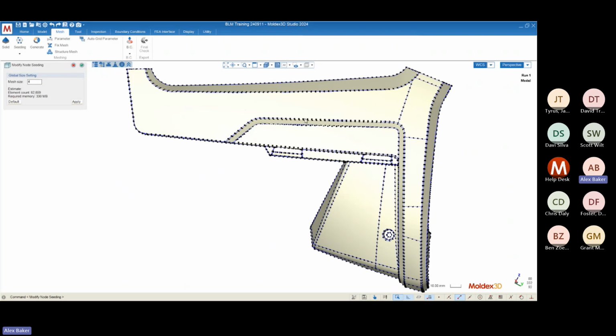But if you use this approach, you'll get more or less a perfect trade-off between the geometry approximation and simulation. I would say that the mesh size of 4 is pretty good for this geometry. You could go maybe a little bit larger than 4, or a little bit smaller than 4 if you're wanting a better geometry approximation and don't care too much about the simulation time.